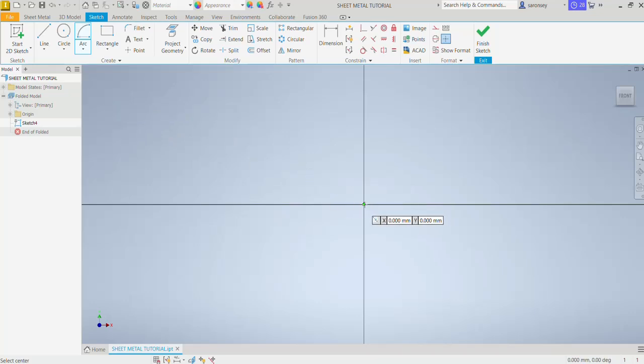Come here to the origin. Let's click in there and then drag it down until you see this dotted circle. So you can click anywhere in between this quadrant. Let's click and then draw our arc by revolving the plus sign around the origin. So we'll click and then right click.